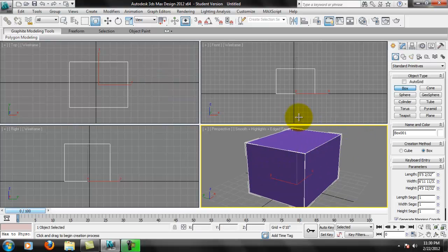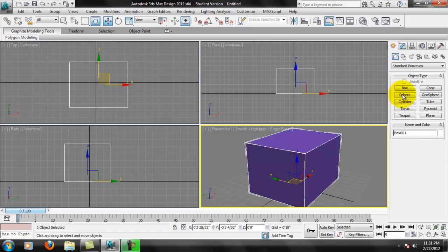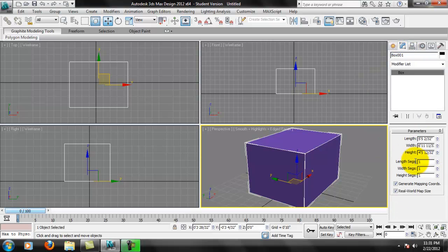Okay, after you actually create a box, we can now jump over to the Modify tab. Don't get stuck changing this. You can change it here, but sometimes this parameter automatically updates to something new, and you'll confuse yourself. So create the box, jump to the Modify tab, and you'll notice it's almost identical, right? So if we go back here, it's gone now, but you'll notice that this looks a lot like the Modify tab, looks like this. So if I want to modify it after I create it, I can.